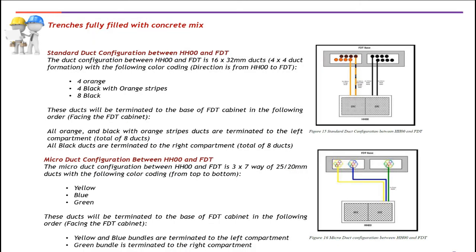In some regions, like Hail in the north, the entire trench is backfilled with full concrete mix without milling and paving. To be able for the contractor to claim for that material and services, they have to use the PU of breaking and reinstatement instead of milling and paving. So in this case, make sure that you are using an M25 concrete mix to cover the trench.